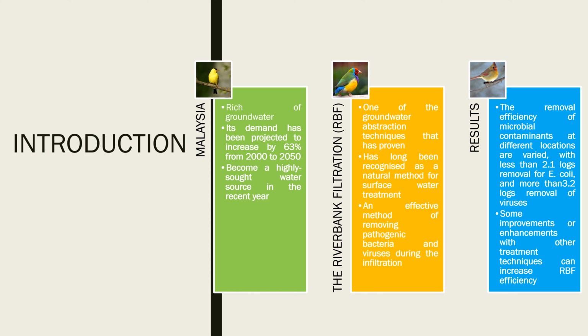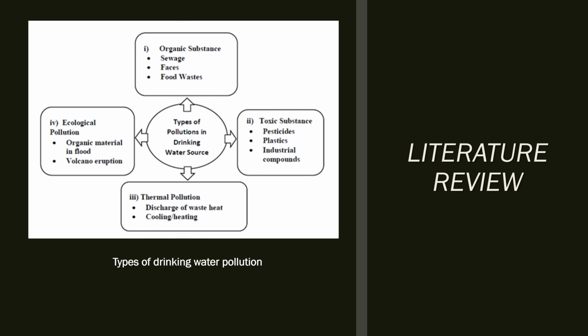The result is that the removal efficiency of microbial contaminants at different locations varied, with less than 2.1 logs removal for E. coli and more than 3.2 logs removal of viruses. Some enhancements with other treatment techniques can increase RBF efficiency.